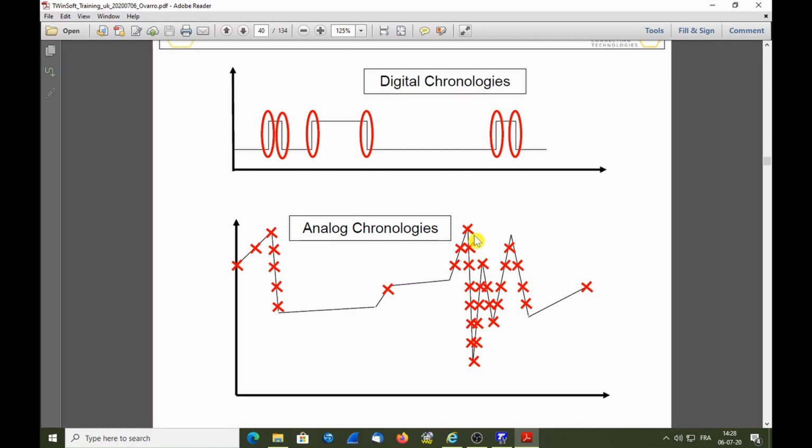Chronologies constitute recording on event, so the variation of the tag will determine the moment when the tag is recorded. If we speak of digital tag, it's the changing from 0 to 1 or the changing from 1 to 0. You decide which event you want to record, variation from 0 to 1 or variation from 1 to 0. You can define that for each tag individually, of course.